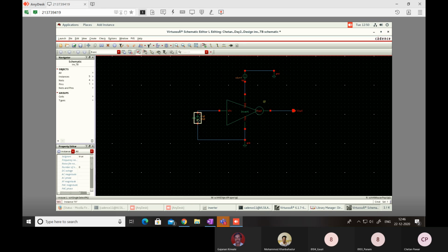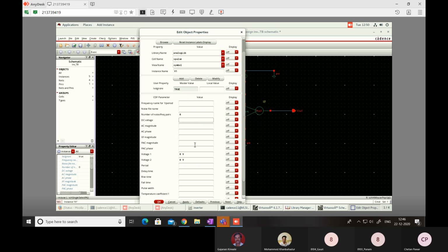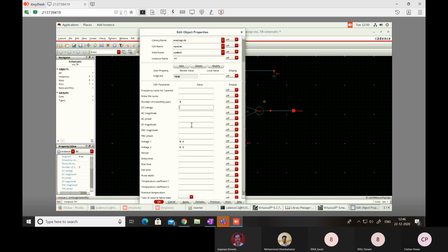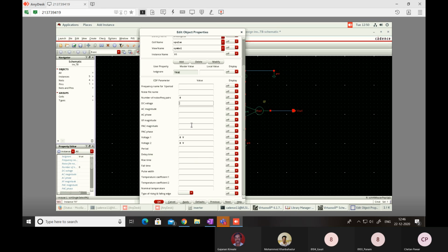Okay. Now connect the sweep, click on the sweep pulse, type Q. Define the voltage pulse. If you select voltage 1 volt, period 100 nanoseconds, so 100 only.